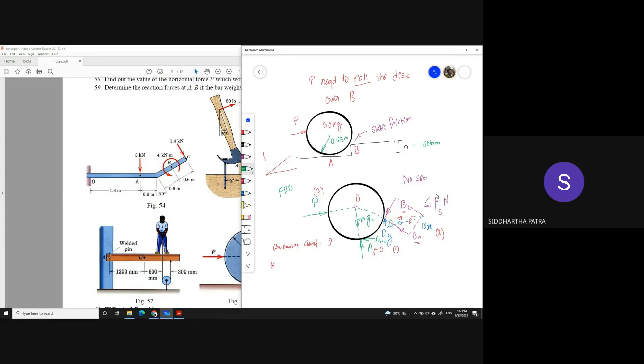So, just by looking at it, if I get the equivalent force system at O, Bt obviously produces a non-zero moment. Bn and P and Mg don't. None of Bn, Mg or P does. Now that resultant moment about O must be zero for equilibrium. Again, I'm just going ahead of myself. So Bt might eventually be equal to zero, but that is simply the solution. That's not the assumption you start with. And that's why you also show Bt in the free body diagram.